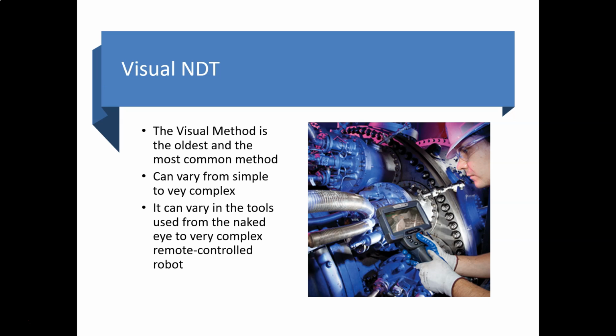The visual test inspections could be done through direct viewing, just by looking at the product with your eyes to discover any discontinuities, or could be enhanced with the use of optical instruments such as magnifiers, mirrors, periscopes, charge coupled devices, and computer assisted viewing systems.